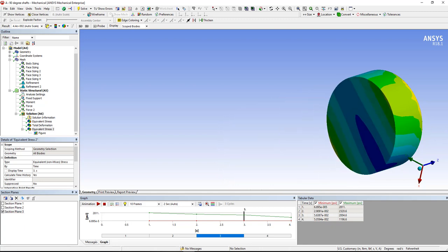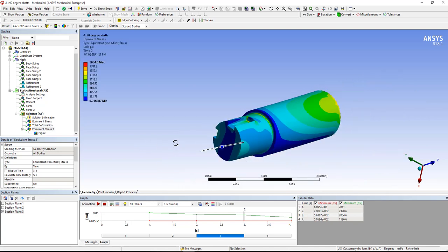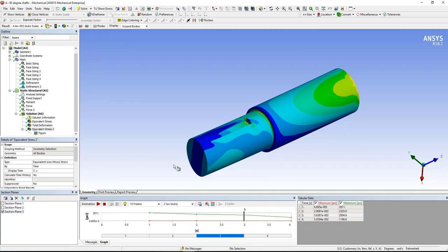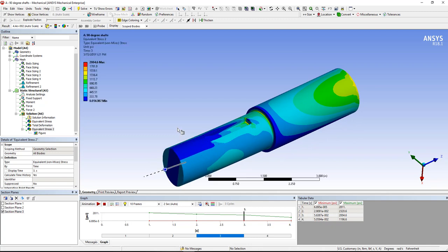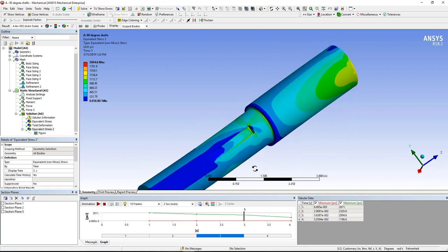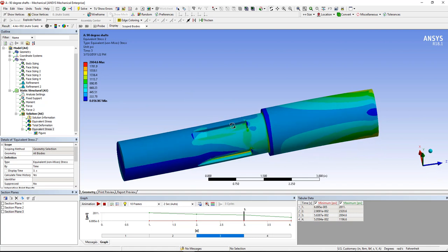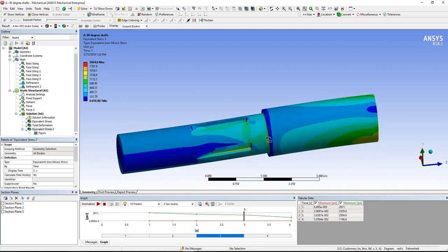But you can see pretty smooth stress contours over here. That's, I think, adequately resolved. Probably more mesh than I need there. But so there's your comparison that you can make for one of these. And again, you make sure it's right for one of them, and then you can repeat with the other geometry.